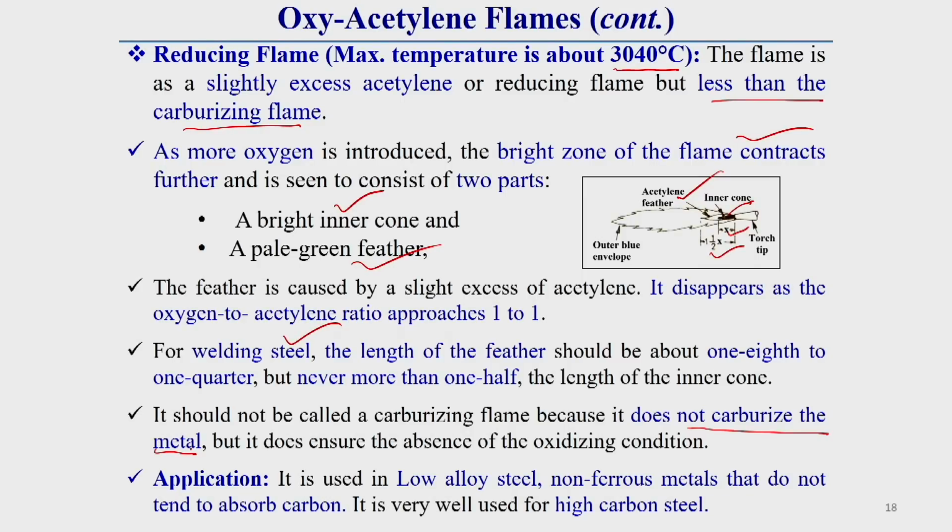Here it should not be called a carburizing flame, because, as I have already told you, it does not carburize the metal. That means it cannot perform surface hardening, but it does ensure the absence of oxidizing conditions.